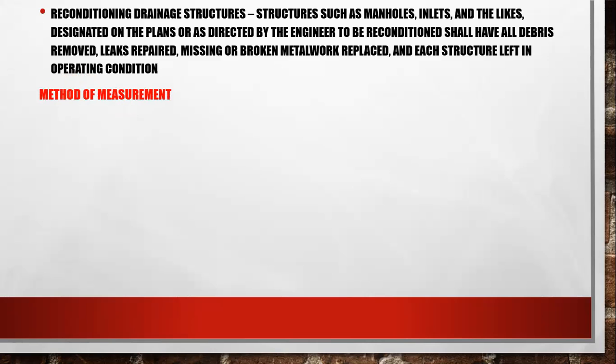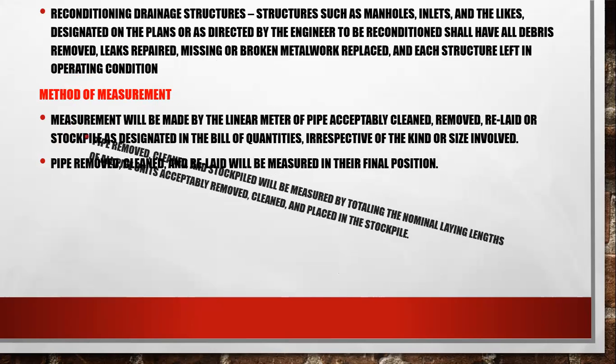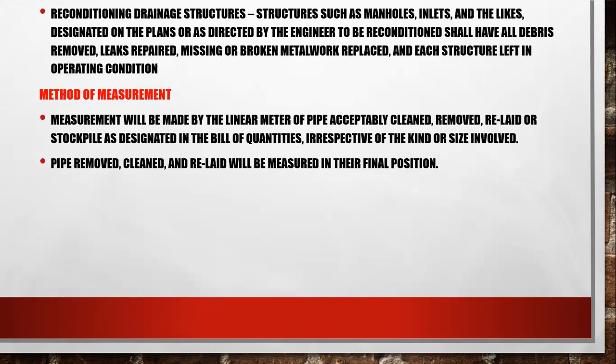So the method of measurement. Measurement will be made by the linear meter of pipe acceptably cleaned, removed, relaid, or stockpiled as designated in the bill of quantities, irrespective of the kind or size involved. Second, pipe removed, cleaned, or relaid will be measured at its final position.